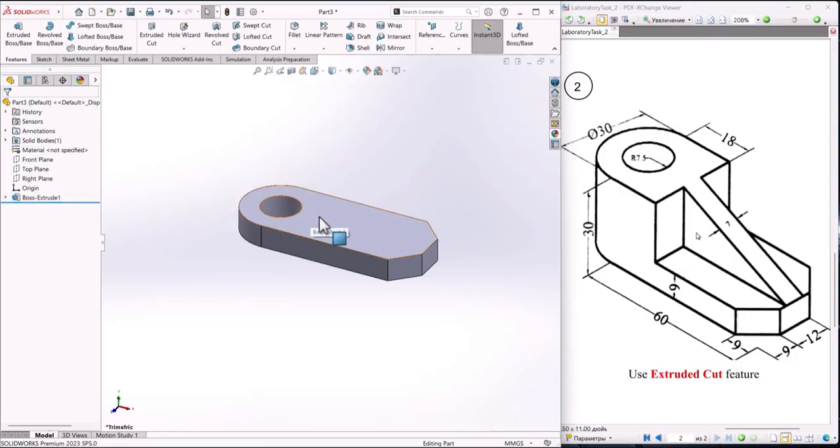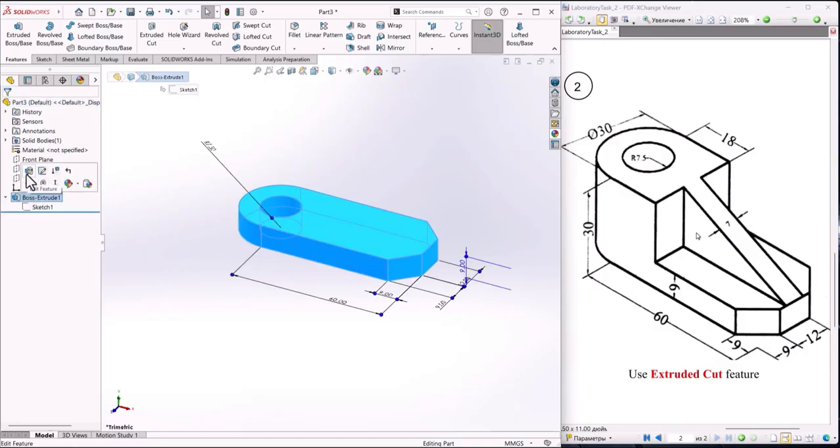And top of this shape, we can draw this side. But how to change this one? How to change, if you want to change, for example, the height of this. I want to make it 30 millimeter height. So just open this and click this first, the extrude one.